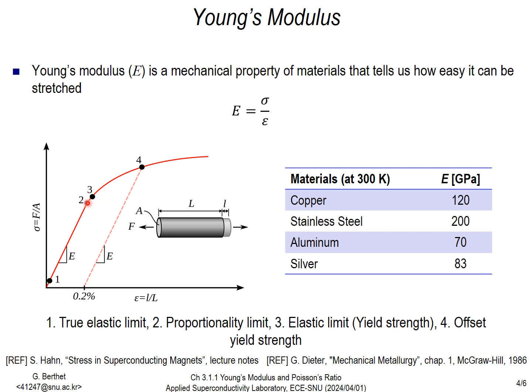Between point 2 and 3, we usually see a small plateau, which is the limit of the elastic regime, also called the yield strength. As of point 3, we're in the plastic regime where irreversible deformation will occur. This means that, for instance, if we stop applying the load at point 4, the material will shrink back, following the elastic regime curve. For our example, the sample has been irreversibly deformed of 0.2% of its original length. On the right-hand side table, some values of Young's modulus are given.